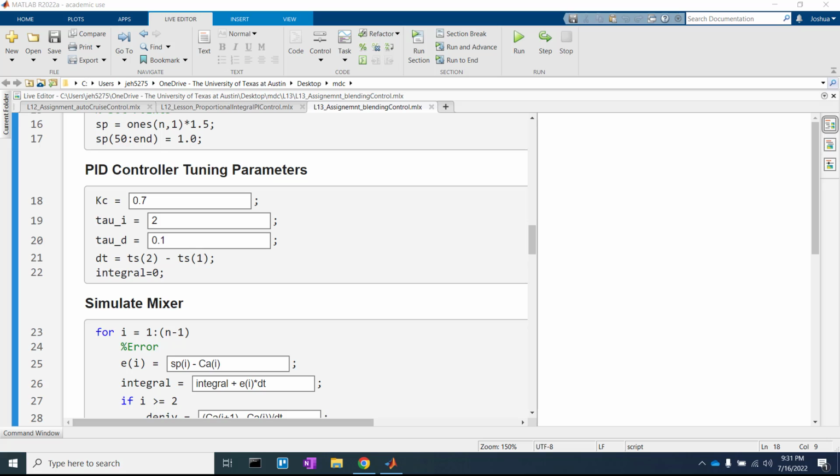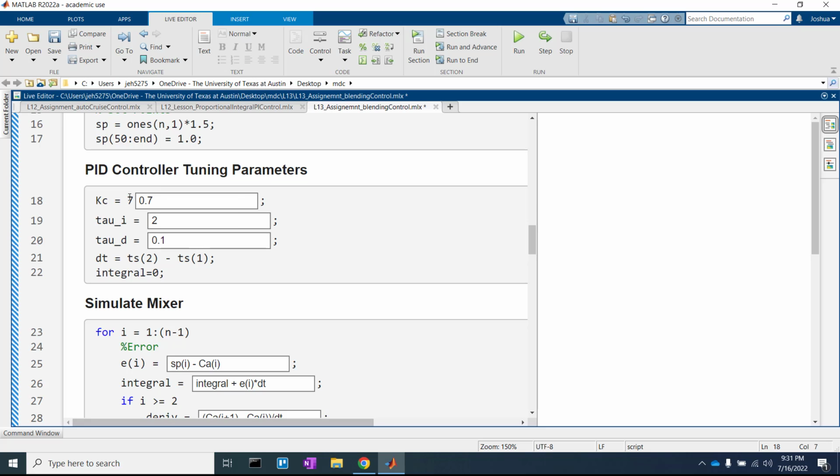We can get these constants from a number of places. Let's just go ahead and set them equal to 1 and then discuss that in just a moment. We'll discuss tuning after this, actually. But the concept is, at least for now, a good place to start is our FOPDT, and make an FOPDT with a step change, look at how that does, and use some IMC correlations.